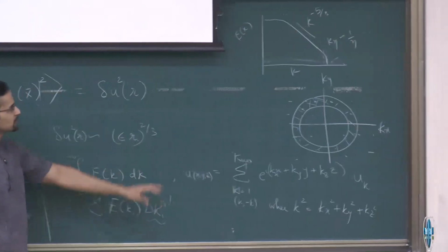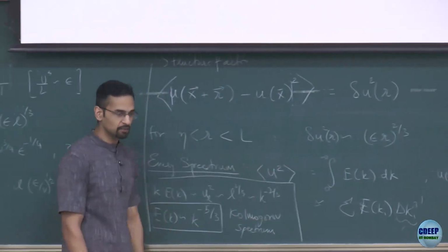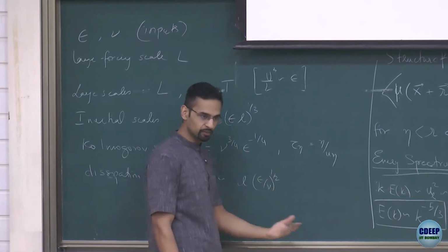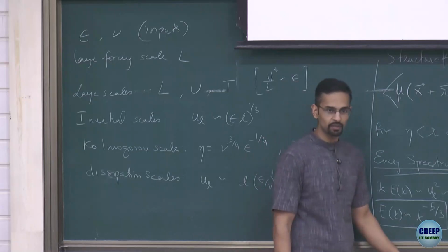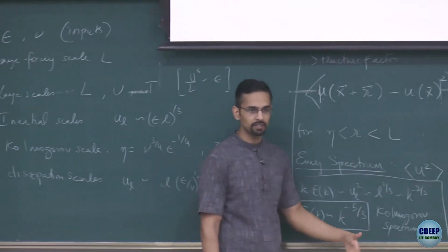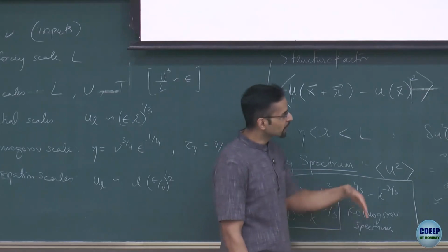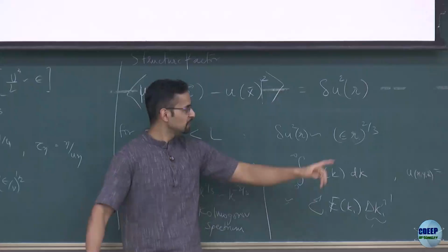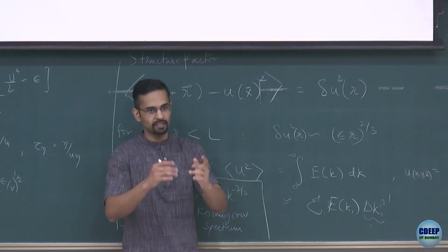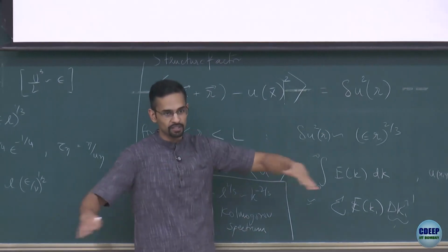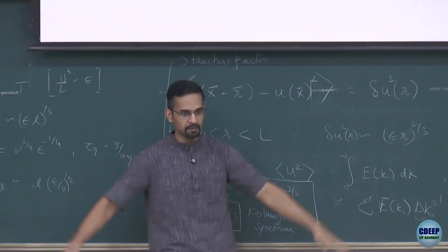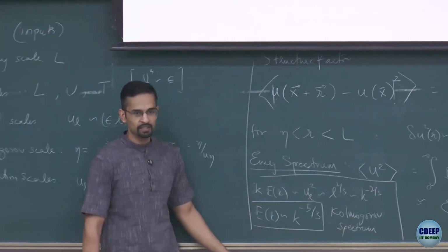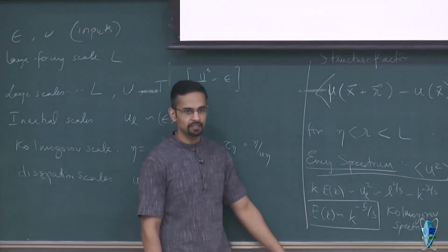And this makes sense because this energy spectra, like the second order structure function, is related to low order moments of the turbulent fluctuations, like the variance. That's in fact the lowest order thing you can get because the mean is 0 in homogeneous isotropic turbulence. But if you look at higher order structure functions, so if you think of the velocity difference as a PDF, this gets the core, it's only the variance, right? If you look at 4th, 5th, 6th order, then you are sampling the tails. These are the extreme events of the turbulent flow. Those start to show deviations from Kolmogorov behavior. These are called intermittency corrections.